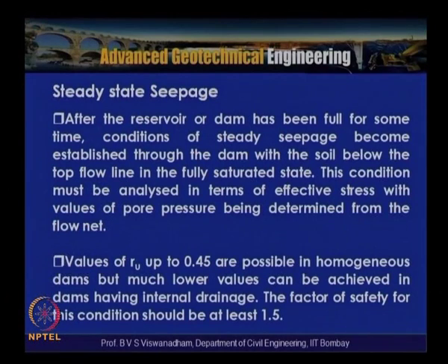The factor of safety for this condition should be at least 1.5, but one thing has to be established: there can be an eventuality of the occurrence of the internal erosion problem. So this needs to be addressed. After the reservoir dam has been full for some time, the condition of steady seepage becomes established through the dam, with the soil below the top flow line completely saturated, and effective stress conditions need to be considered.